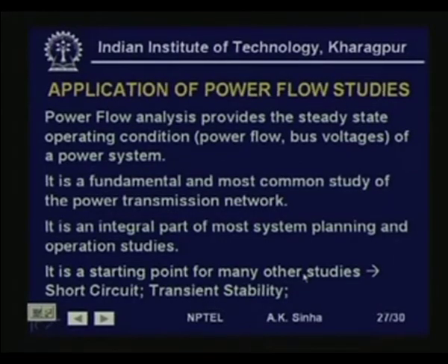Even if we want to do an economic dispatch for the system, then also we need to do this study. We need to know the operating condition, and only then can we think in terms of finding out what the generations should be. And if we get an economic generating schedule, again we will need to find out the steady state operating condition to check what the power flow is going to be in each of the transmission lines, what the voltages are going to be, and whether all these values are within the limits or some limits are violated. So, all these things need to be done, and for all this we need a load flow analysis to be carried out.